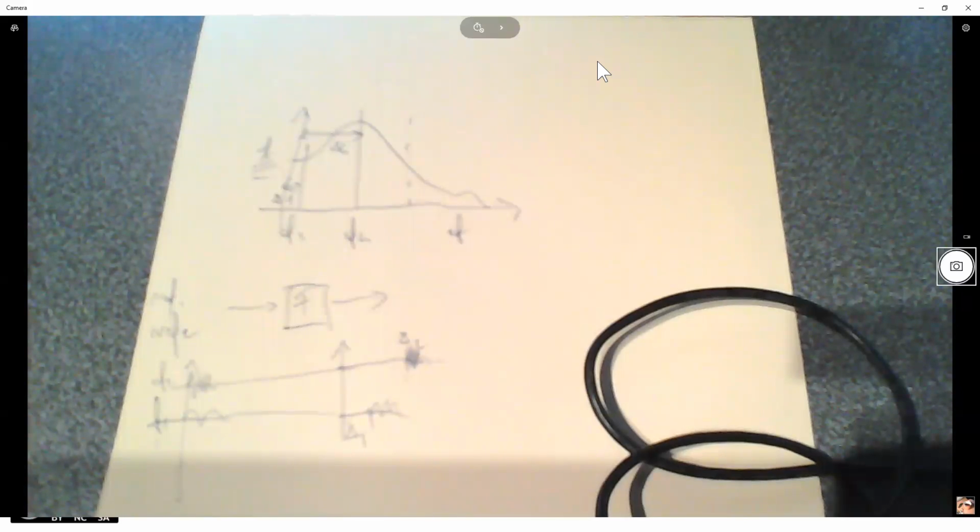If you want to reconstruct that signal, you need to take into account this non-constant group delay. So you can design the group delay to compensate for this wavelength dispersion. So two frequencies always have different delay.